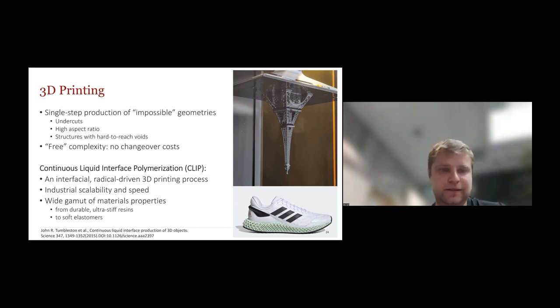Specifically, I'm working on continuous liquid interface polymerization and applying that to high resolution 3D printing. So this is an interfacial and radical driven 3D printing process. Over the past about 7 years, it's been proven to be industrially scalable.